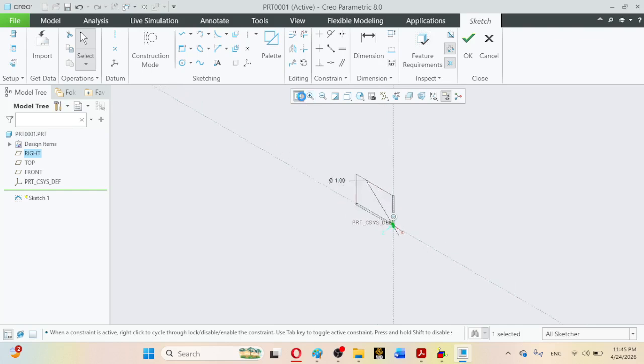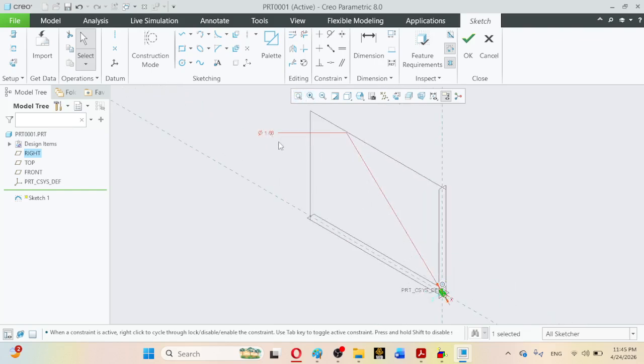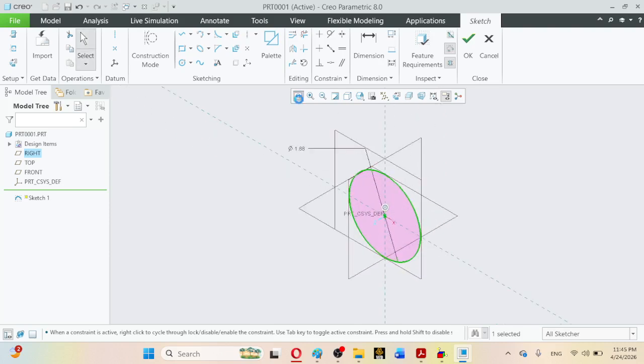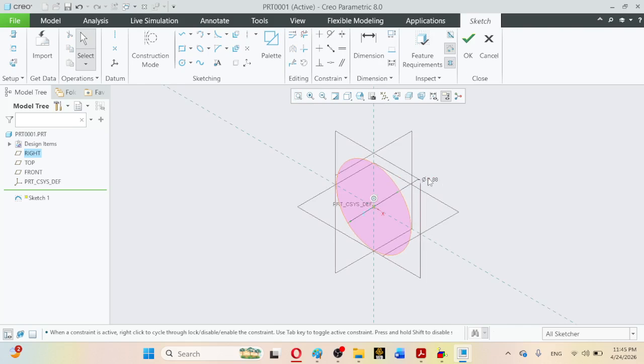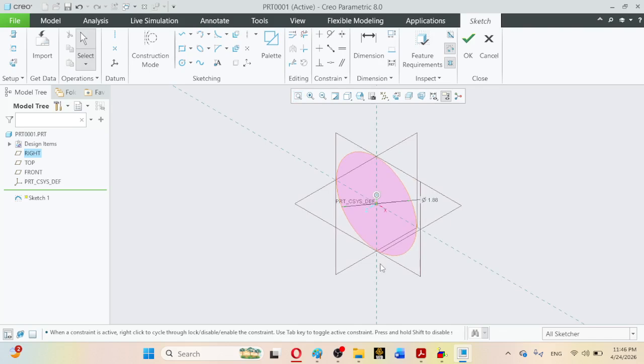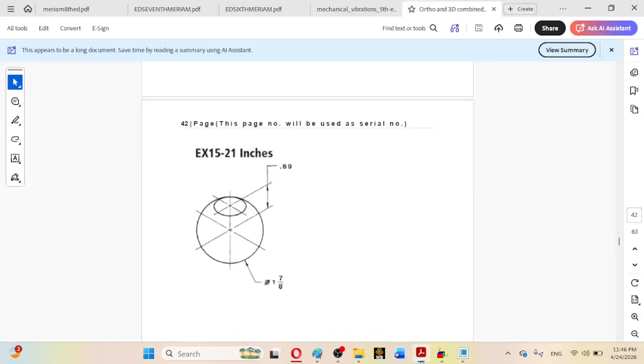So here just bring this dimension near to the origin, near to the model, and you will be getting a better zooming capability here like this. For example, you can show it here like this. Again, just zoom out, and here again you can bring it further and near, like this. As you can observe here, a better zooming has been shown.